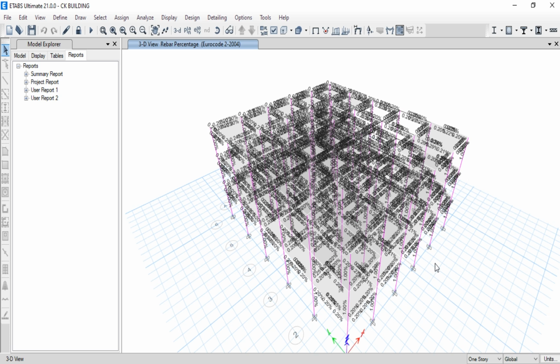Knowledge about construction. So in today's session, we shall look at designing an RCC structure in Etabs. This design will help us to get the steel values we shall use in detailing and giving to the clients for the construction. So the first step we shall do is make sure that our model has been analyzed.